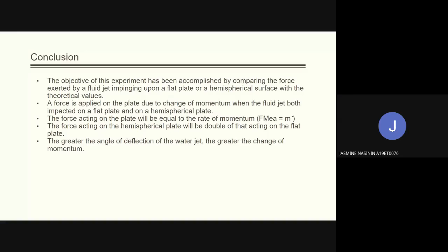Next, the force acting on the plate will be equal to the rate of change of momentum. And next, the force acting on the hemispherical plate will be double that acting on the flat plate. Lastly, the greater the angle of deflection of the water jet, the greater the change of momentum.